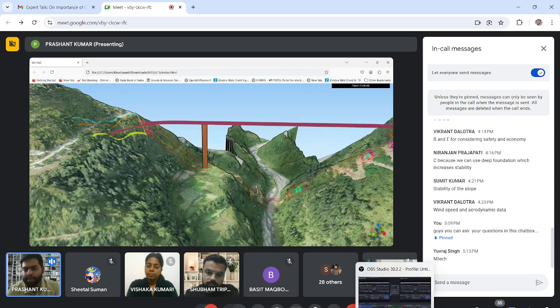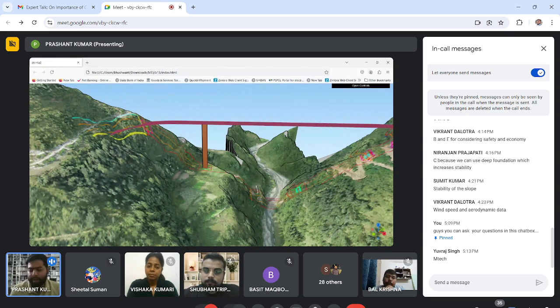For rock class classification, if you have some data, like someone would have done some MTech or PhD thesis on some of the tunnels, you can just take that data and draw it on a plan, a QGIS map, and see how the class of rock is varying, and then connect it with the geological fault and try to establish some correlation. So that's how we can do it.